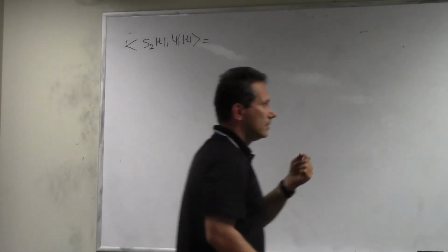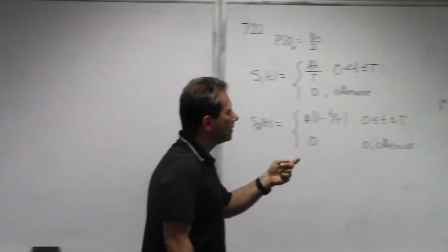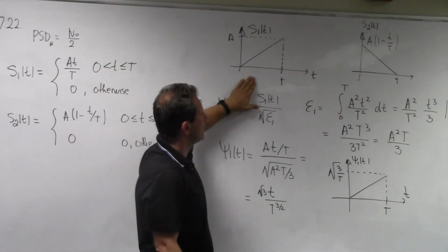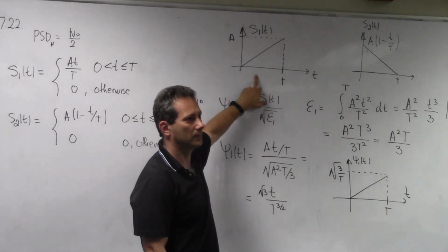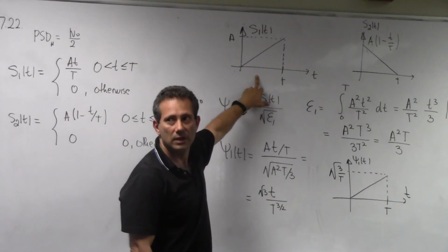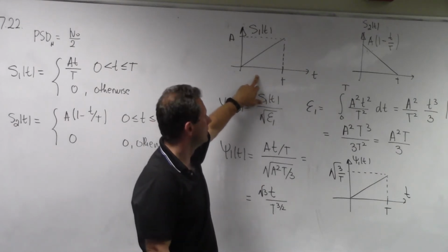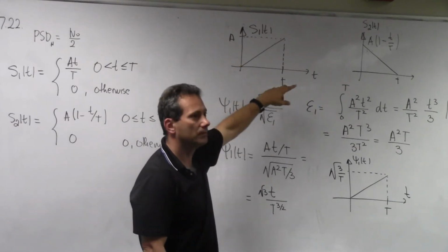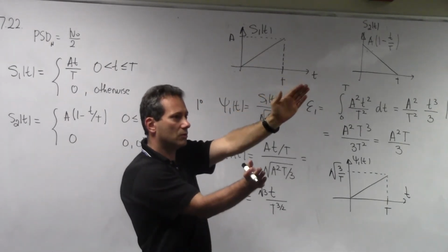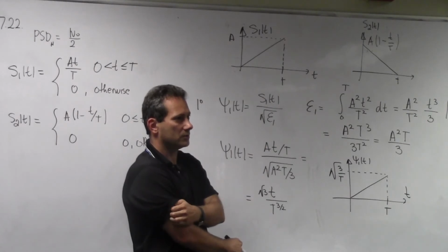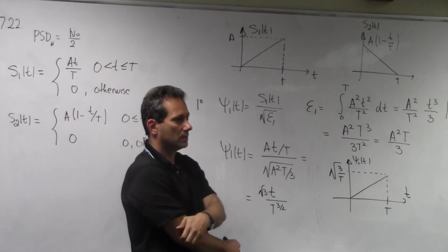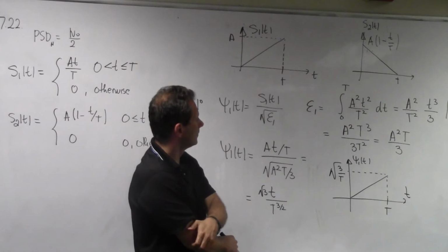Wouldn't it just be a matched filter for each of those? Well, you can do that, but here's the problem with it. These two are not orthogonal. I don't know if that would be the optimal receiver. If you just match these two, then you're projecting over non-orthogonal vectors. So is the matched filter only optimal when they're orthogonal? I think so. Yeah, you have to make them orthogonal.